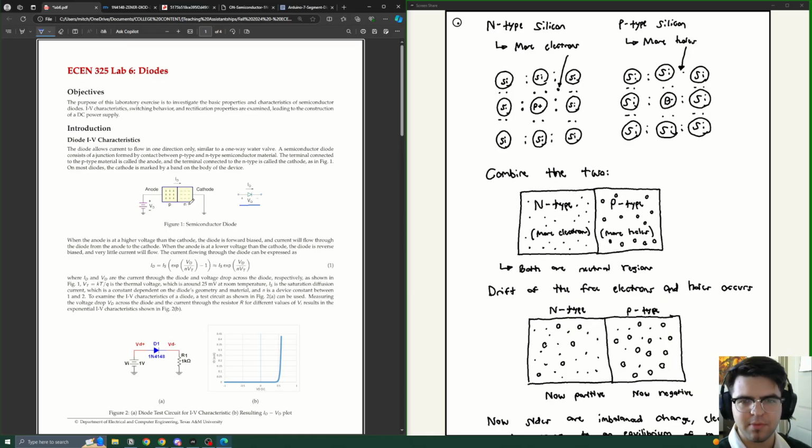We dope these silicon metals with a couple other types of things called dopants. These are different elements on the periodic table. For example, for N-type silicon, we put little bits of phosphorus in there, which donate an extra electron. So phosphorus has 5 valence electrons, and we want to fill up its valence electron shell with 8. So we put it in our silicon metal, and it will bond to the others to fill up its valence shell, which donates another electron into the whole metal.